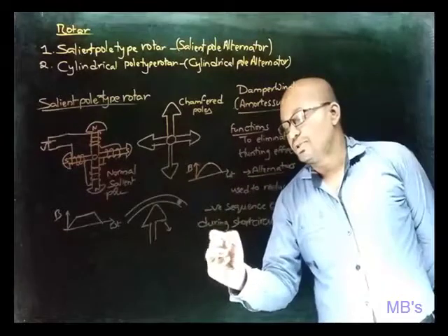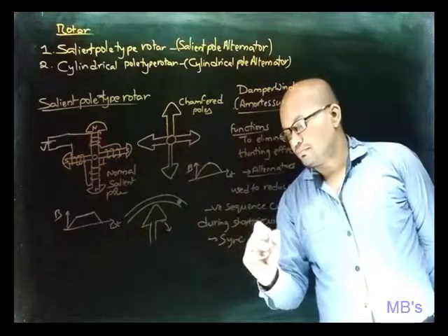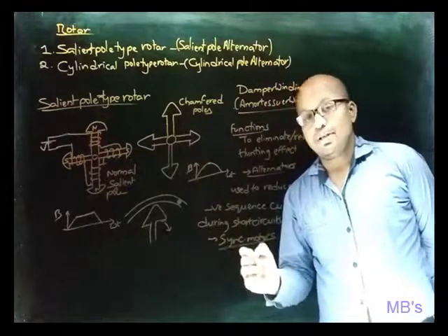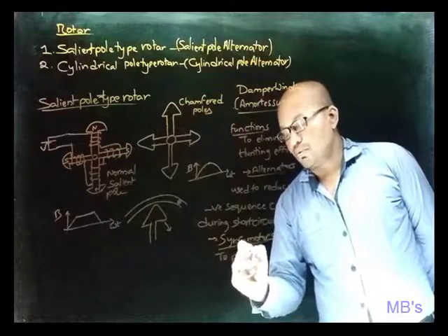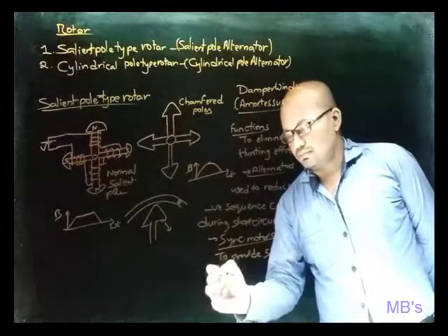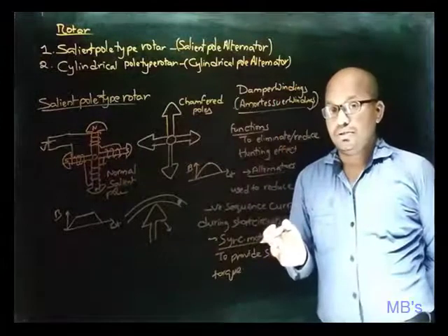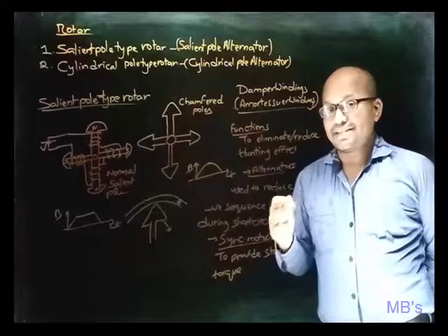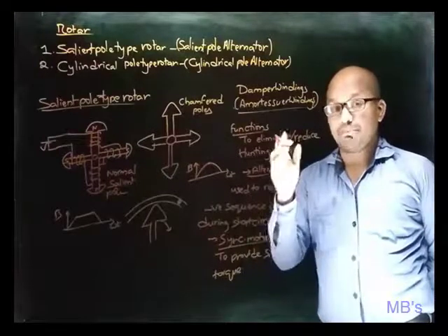And in the case of synchronous motors, damper windings are provided to give starting torque. We know that synchronous motors are not self-starting, so there is a necessity to provide starting torque, which can be provided by using damper windings.